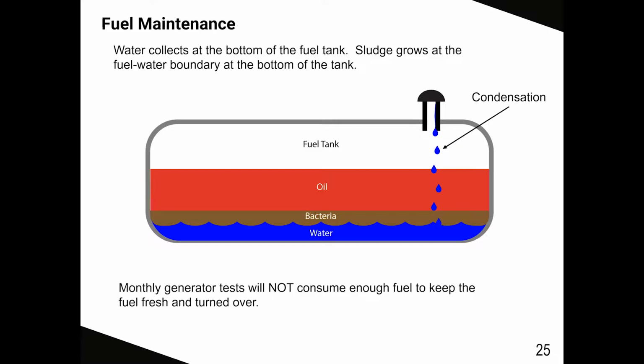drop tube. So Ed, with this bacteria interfacing with the water and the oil, how does that affect a steel tank? Well, steel tanks don't like that water down the bottom of them, that sludge. So yeah, there has been some premature failure of steel tanks, especially with those ultra-low sulfur and biofuels.